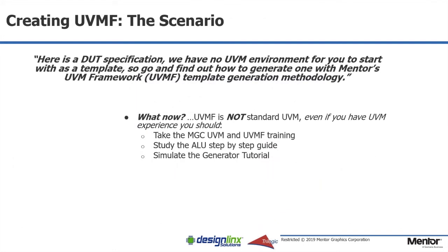So what's the scenario here? Quote, here is a DUT specification. We have no UVM environment for you to start with as a template, so go and find out how to generate one with Mentor's UVM Framework, UVMF, template generation methodology. So what do you do now?